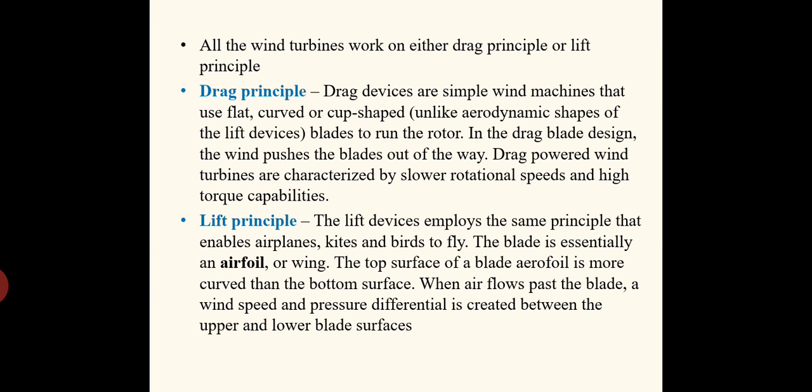Some streamlines of the air will flow through the upper part of the blade, and some through the lower part. I have already told you the upper part covers a longer distance compared to the lower part. Due to that, a pressure difference is created, and due to that pressure difference, a lift force is created always perpendicular to the flow direction. That perpendicular force pushes the blade from the lower side to the upper side.